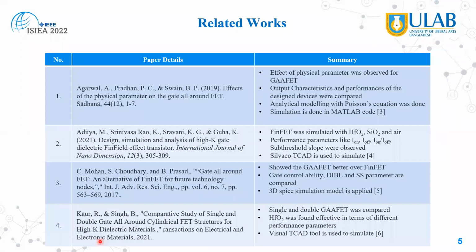Moving on. So these are some related works. In the first paper, you can see they observed the effects of physical parameters for GAAFET. They compared the output characteristics and performance of the designed device. They used analytical modeling with Poisson's equations here. In the second paper, they simulated FinFETs with hafnium oxide, silicon dioxide, and air. They observed the performance parameters. They used Silvaco TCAD to simulate.